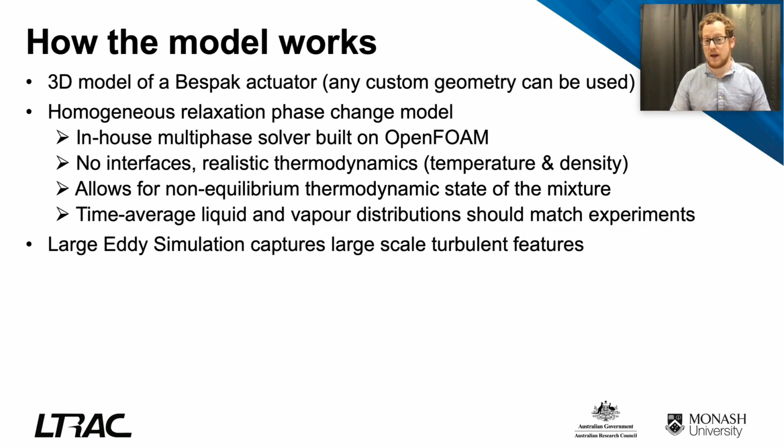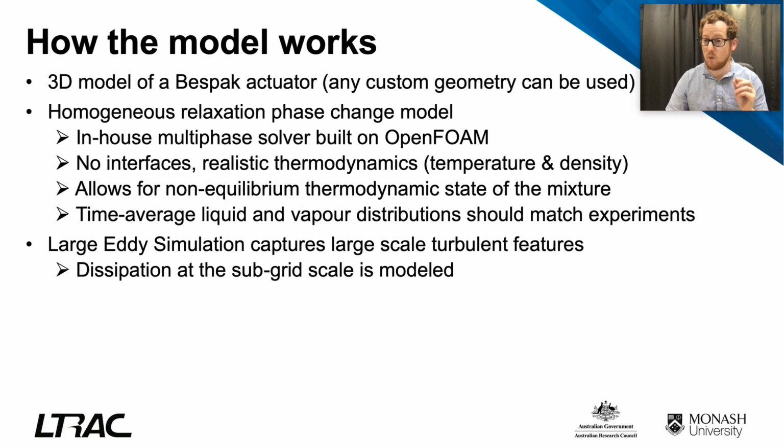We also have to think about turbulence. We use an approach called large eddy simulation. Large eddy simulation captures the large turbulent coherent structures responsible for entraining warm humid air into the cold jet of propellant vapor. That's quite important for the development of the spray. And then anything that's smaller than the size of our grid, we use a model to capture the dissipation of that energy. Now this is in the literature. Most models for MDIs in the past have used Reynolds averaging, which doesn't capture these effects. And this is quite important, especially when it comes to water transport, as we'll show.